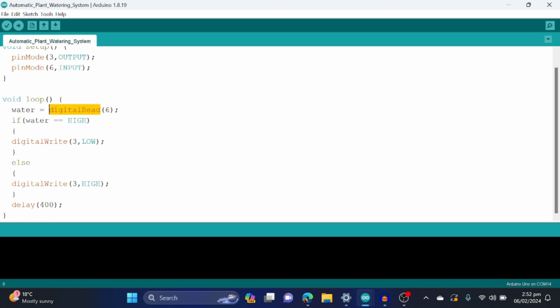That value should be a 0 or a 1. Once we are done with the hardware setup as well, you already know there is this magnifying glass termed the serial monitor. Once you are connected with the Arduino, the setup is there and you have uploaded the code, then in real time we will open the serial monitor and see whether the water variable is getting the value, whether the input is coming or the output is going. This is the thing for debugging which we will be seeing later inshallah.